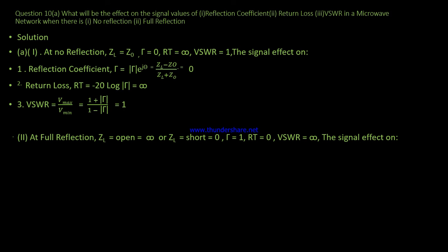At full reflection, the load impedance is open, which is infinity, or we can say it could be shorted, so ZL is equal to 0. The reflection coefficient is 1. The return loss is 0. The VSWR is at infinity.